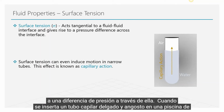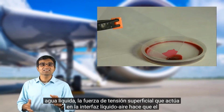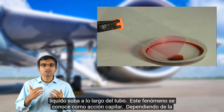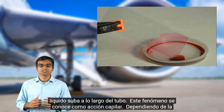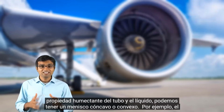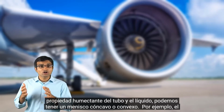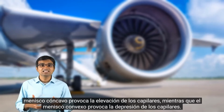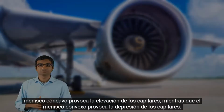When a thin, narrow capillary tube is inserted into a pool of liquid water, the surface tension force acting at the liquid-air interface causes the liquid to rise along the tube. This phenomenon is known as capillary action. Depending on the wetting property of the tube and liquid, we can have either concave or convex meniscus. For example, concave meniscus leads to capillary rise, while convex meniscus causes capillary depression.